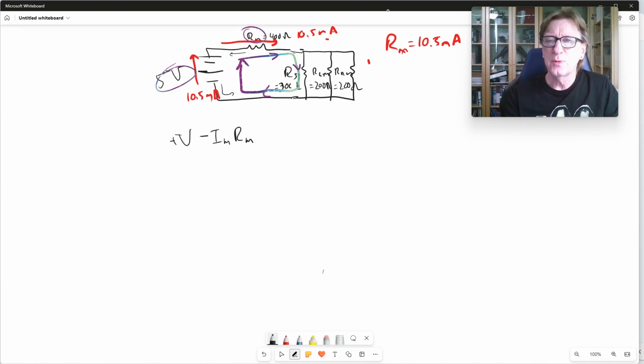Okay, now I'm going to come through here. I'm still going against the electron flow because the electrons are coming up this way and then they branch up this way. Because remember, they're going to split. I'm going to have some going up each one of these branches here. That's what makes them in parallel. So that means it's going to be negative, and I'm going to have, let's do the current first just to keep them the same, IS over RS. And then I'm back to my voltage source, so that's equal to 0 by conservation of energy. So this is Kirchhoff's loop rule.